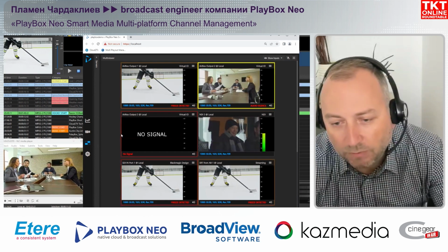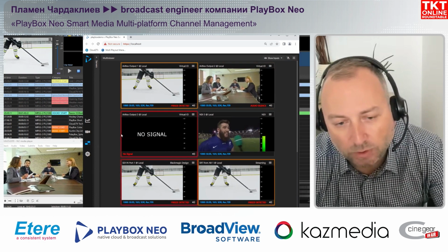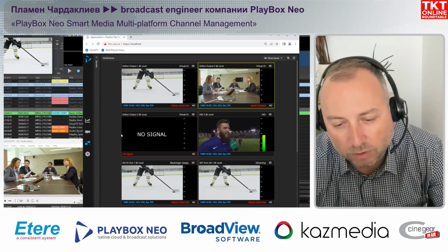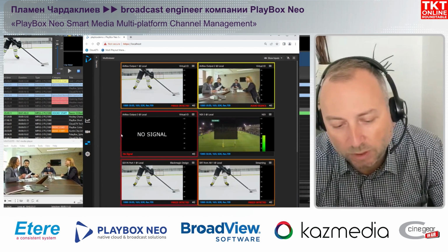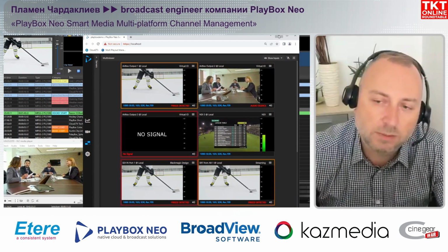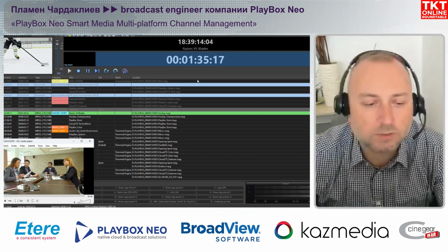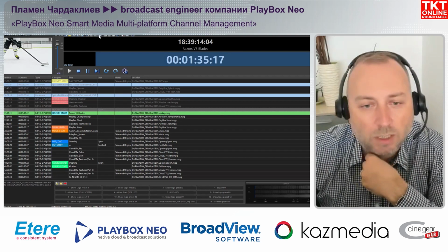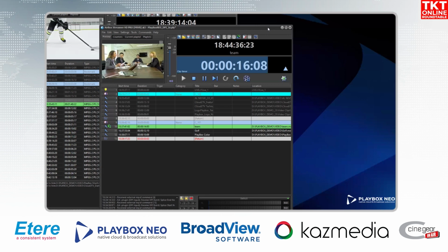The other feature I want to mention is that we support SCTE triggers for both SDI and SRT or UDP output. So we are supporting SCTE 104 for SDI, both on input and output, and SCTE 35 for the SDI, both on input and output. So our playout can be a sender or a receiver. Let me make quick demonstrations again for this.